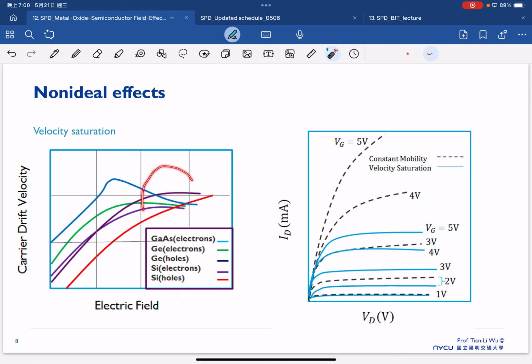So at that moment, velocity saturation becomes one of the important considerations if we want to make an RF power amplifier. And for sure, right now none of these materials are good for the power amplifier. The one that people believe is ongoing, and already happening now, and will continue to dominate is gallium nitride, because gallium nitride has a very good saturation velocity.